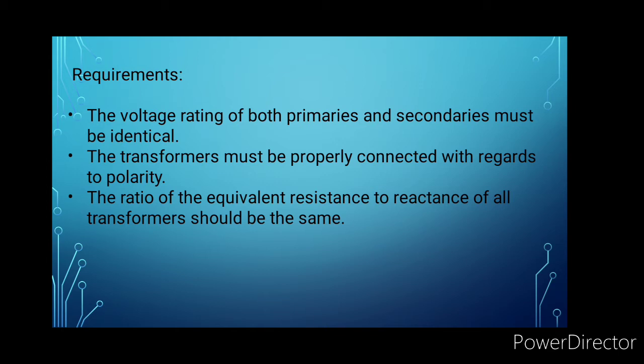Number 3, the ratio of equivalent resistance to the reactance of all transformers should be the same. Why? If there's a difference between two transformers in parallel, it results in a different phase angle.